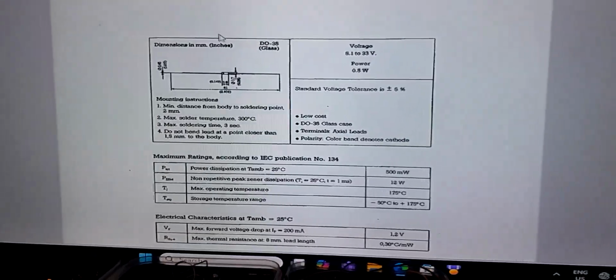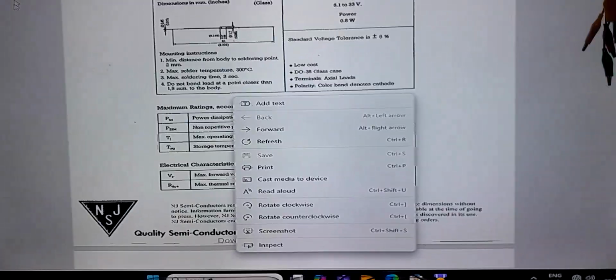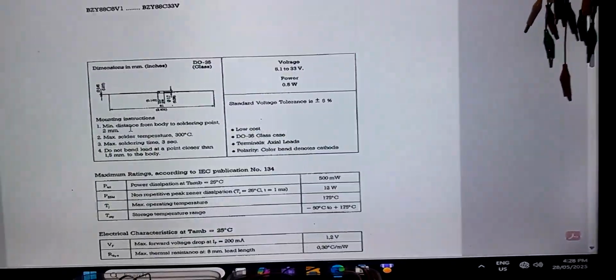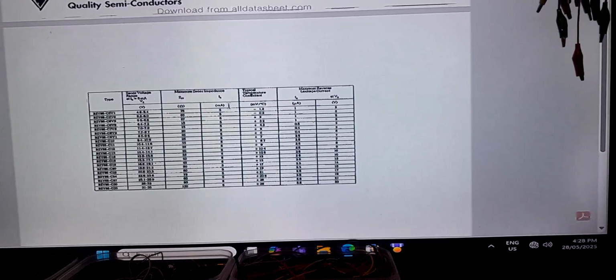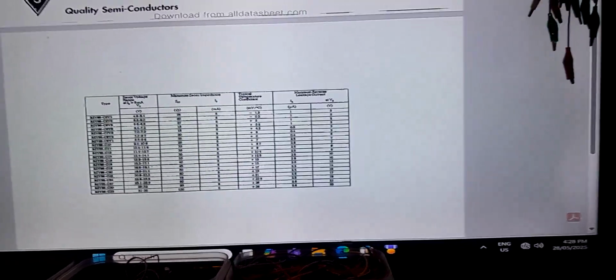Honestly, there's not going to be much difference, because this is the diode that they're using for the 37 volt source, and the 3.6 volt diode was the one on the 5 milliamp source. And if we look at it, see, IS milliamps 5. I'll just make that bigger because, yeah, they're all spec'd at 5 milliamps.